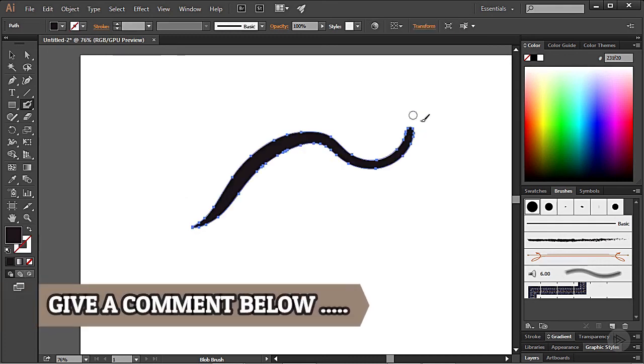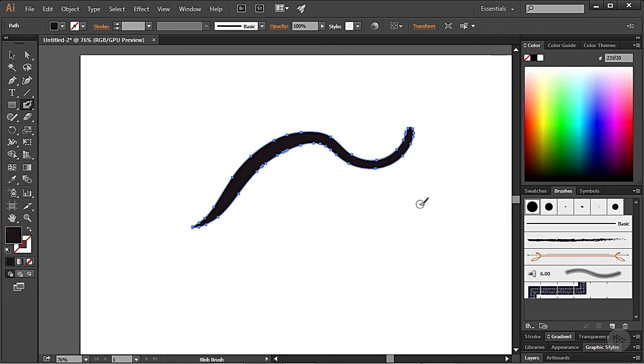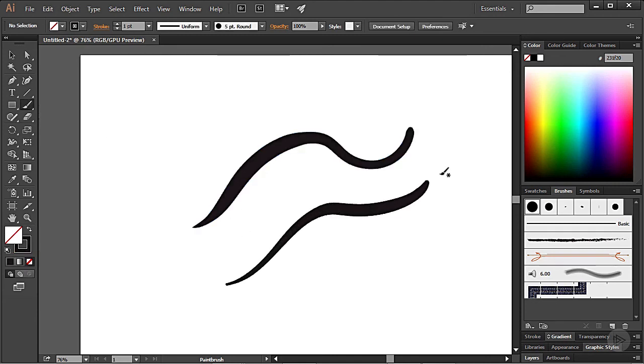So I'm just going to draw, and you could see right away it's showing the anchor points in the paths. So it's not a stroke in the traditional sense that you have a stroke path. Now, if I draw a very similar stroke here, except with the brush tool right here, and I take my move tool and I click on it, we'll see that we have just a single path right here, and it has a stroke. And that's how this is adjusted.